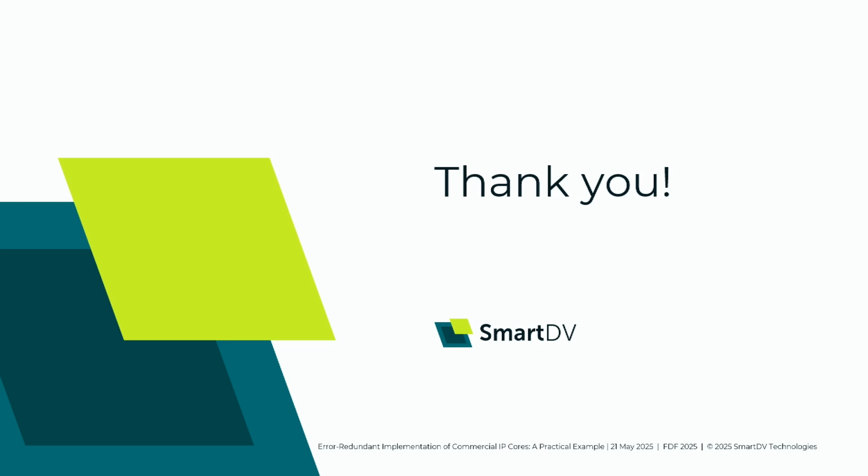Yeah, thanks a lot for the question. So as said, we have two different portfolios. So one is the design IP that is developed in plain Verilog RTL. With the design IP, you will always get a test bench. You will always get sample code, you will get constraints and appropriate reports. When it comes to the verification IP, this is much more comprehensive deliverables, so you will get full test cases with randomization and a lot of test scenarios that are delivered together with the VIP.